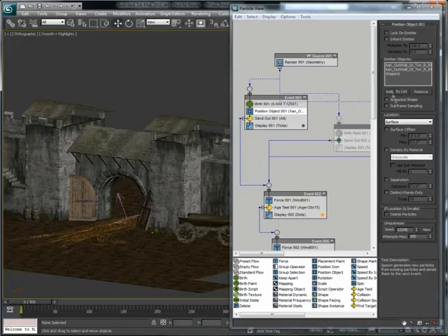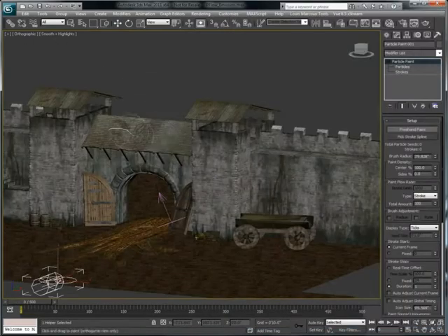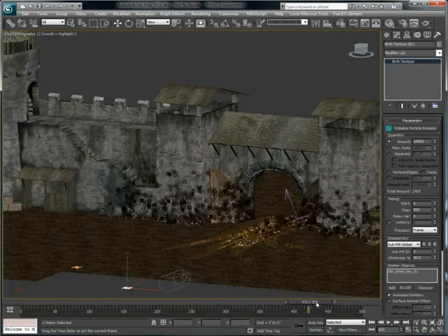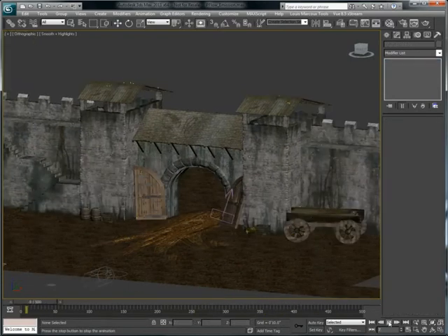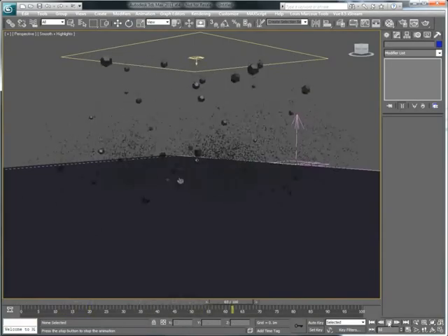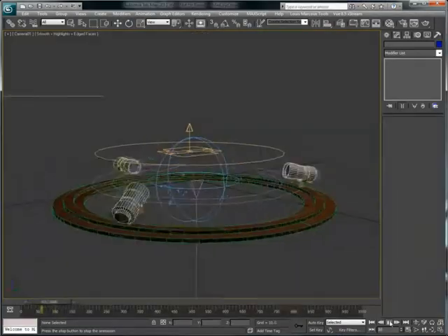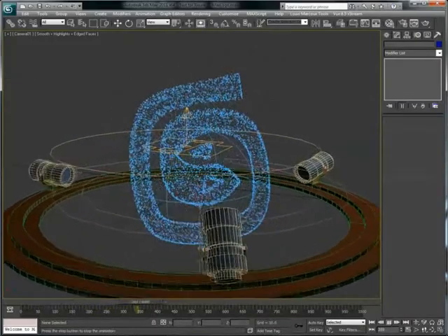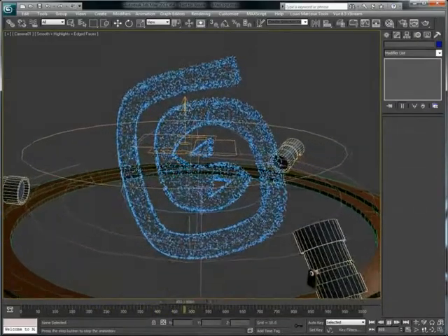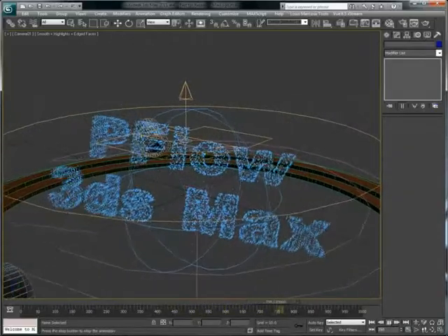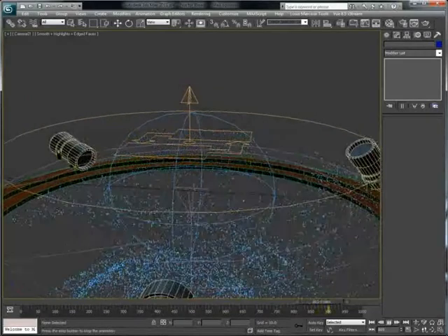Particles can emit from objects or sub-objects. You can paint areas where particles will be emitted, or you can use animated maps to create animated emitting areas. Then particles can be affected by all sorts of forces, enter in collision with objects and change their course of action, stick to objects, or many other effects that you can think of. Particles can be made of standard shapes, or they can use instance geometry in the scene. Exploring pFlow really opens a completely new universe of possibilities in 3ds Max.